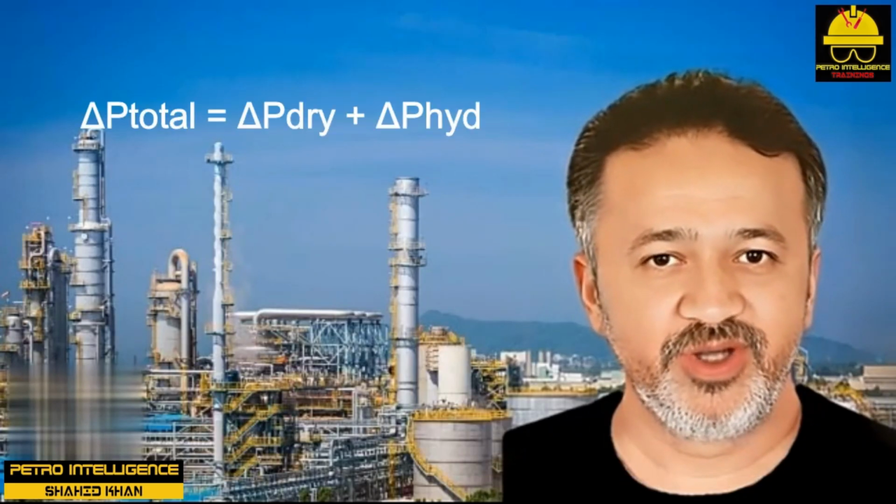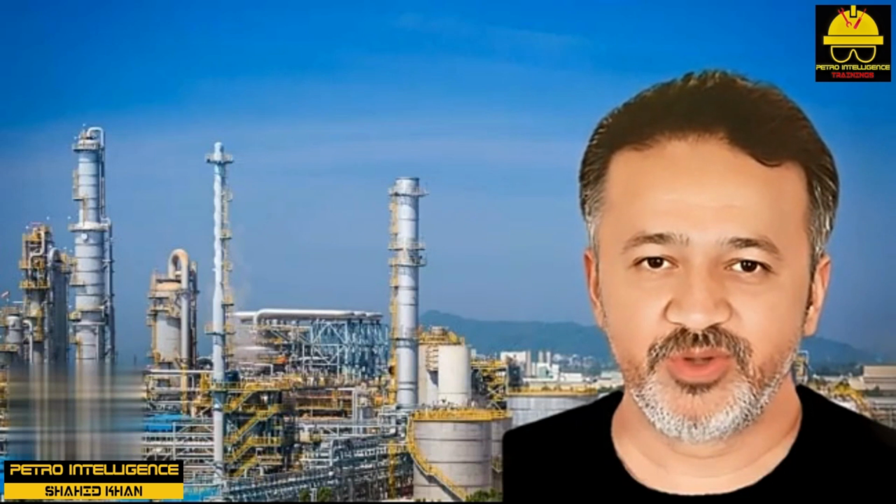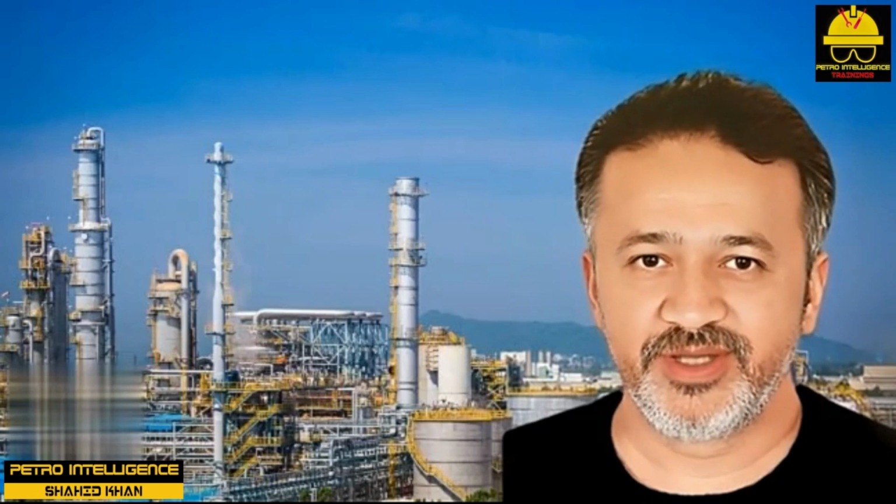Calculated total tray pressure drop. The sum of the dry tray pressure drop plus the hydraulic tray pressure drop equals the total tray pressure drop. Increment P total equals increment P dry plus increment P hydraulic, expressed in inches of clear liquid.